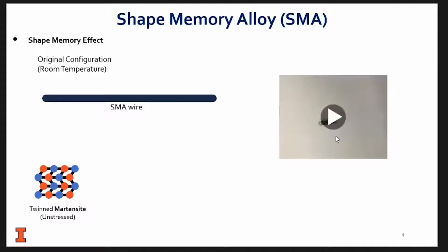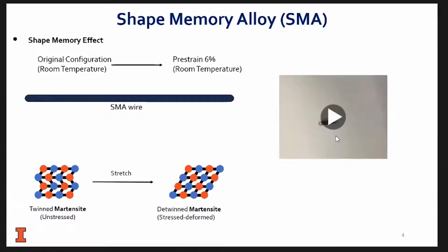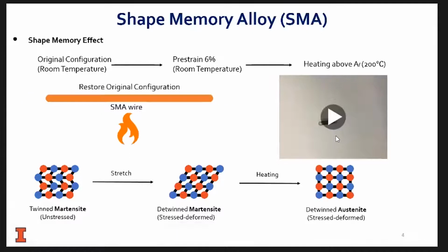It's called shape memory alloys, or SMAs. Now, when you look at SMAs, it's like any metal, no different. When you stretch it, it elongates permanently. And the key here is that when you heat it up with any method, it shrinks back to its original shape. So you think it's permanently formed, but it's not. And that's the beauty about it. Now, the good thing about this is if you hold it back and prevent it from recovering its original shape, it's going to pull back very strongly. That's the recovery stress, or the pre-stress force. So instead of using hydraulic jacking or stressing, we're using temperature. And that gives us great versatility in the design.